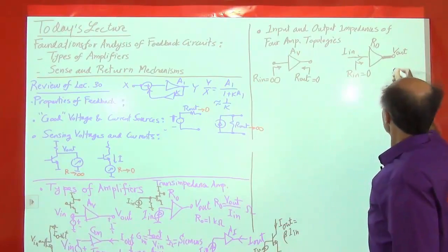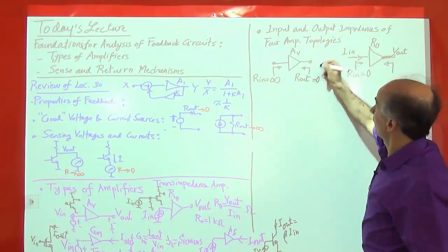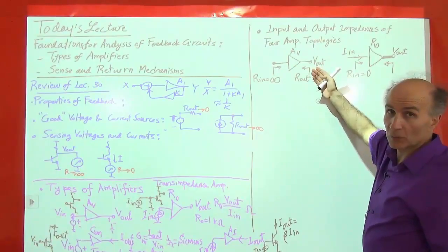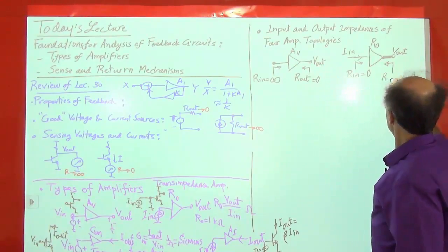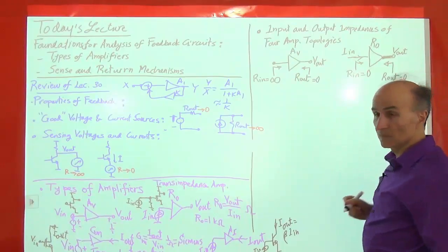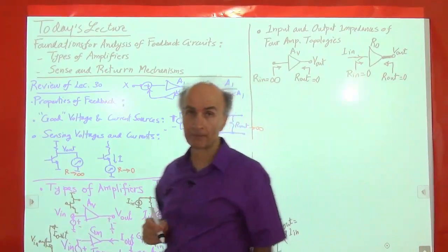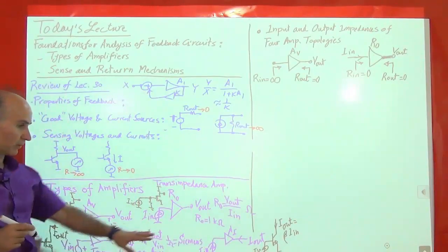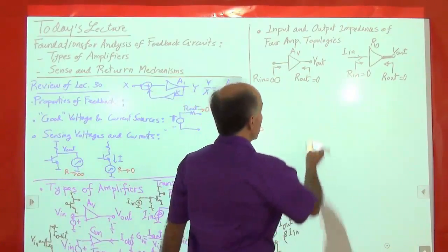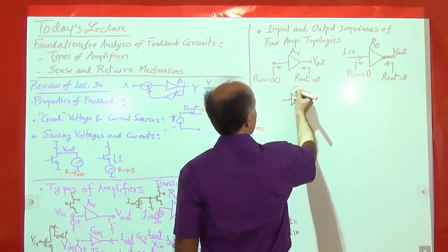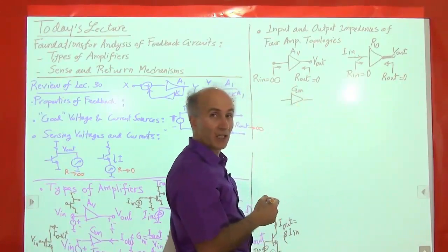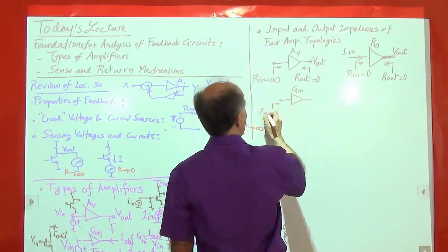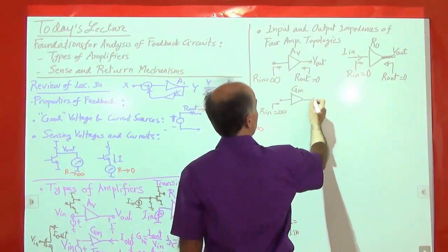All right, how about the output resistance or output impedance? Well, that's similar to before because here we also have an output voltage. We're trying to deliver a voltage, so we want to be a good voltage source. So then this should be zero. All right. Okay, so now very quickly we can see how it happens for the other two, right? Because these are just extensions of these. So if we have a transconductance amplifier, sometimes we call this just a GM stage, then because we are sensing a voltage, this should be infinite.